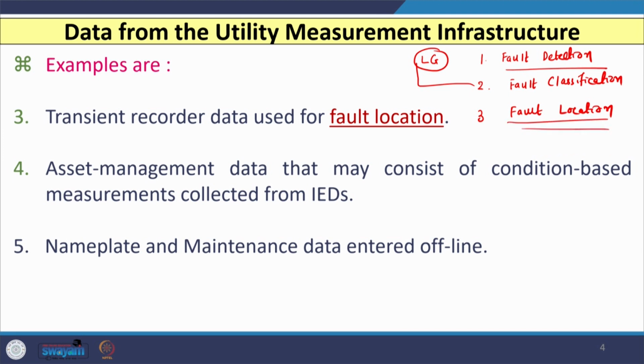So, in fault location algorithm, the estimation of fault is carried out, and this algorithm will tell you that from this substation, or from this sending end, or from this local end, at a distance of let us say x kilometer, there is a probability that the fault has occurred, and then you can carry out the required maintenance by sending the lineman or the crew.